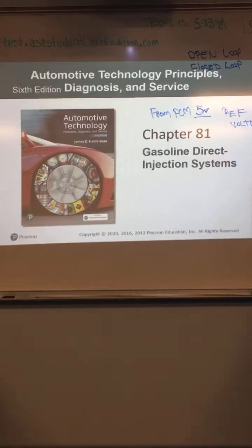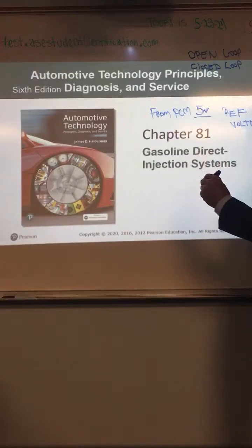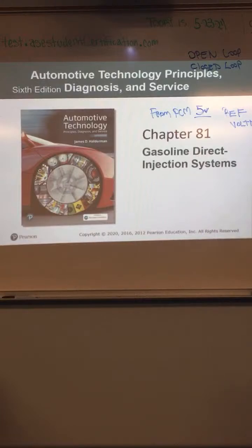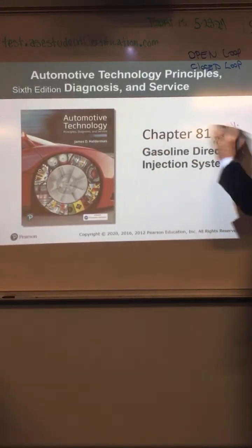The question in the book reads, port fuel injectors operate on 5 volts from the computer. Is an injector a sensor? It's an output. Is an injector a sensor, yes or no? No, it is not. Could an injector operate on 5 volts? Not a chance. 12 minimum. So A is wrong, okay?